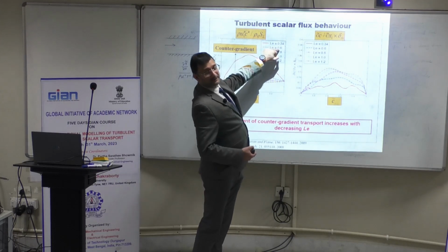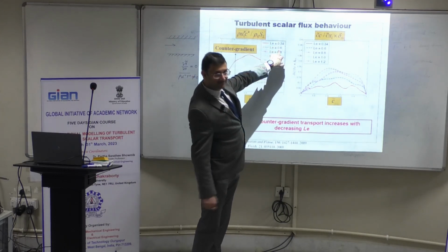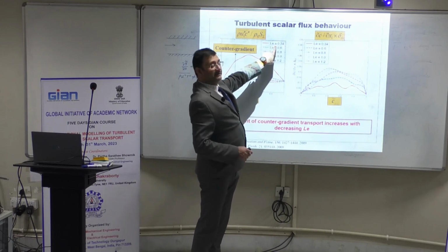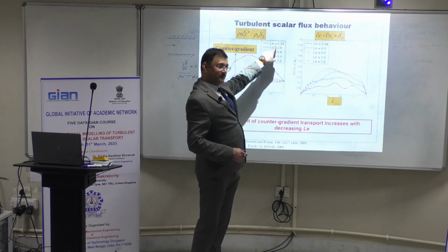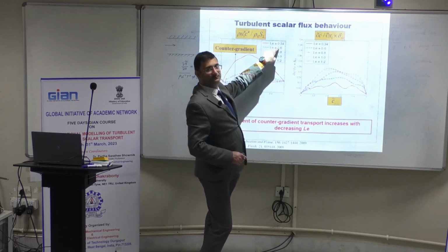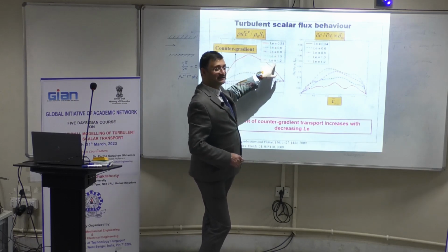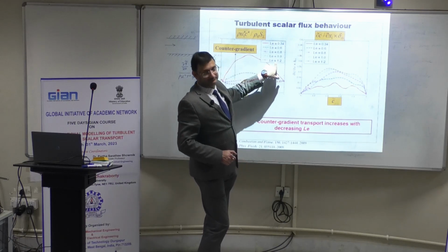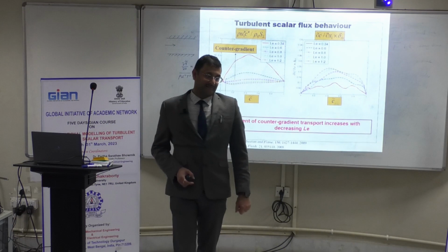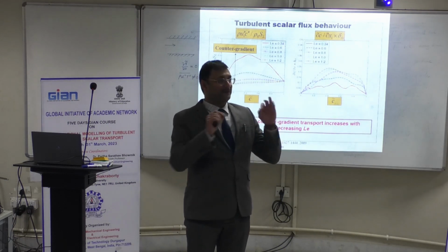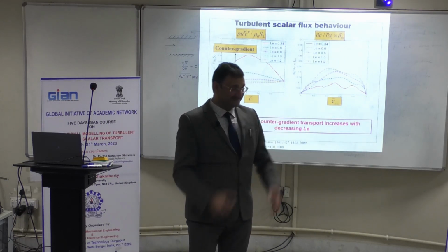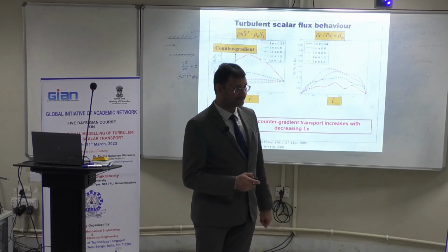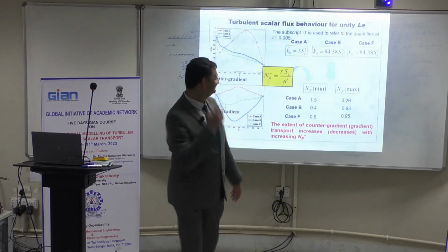Here you have about 40% hydrogen by volume mixed with methane. This is a hydrogen air flame for equivalence ratio 0.4, and this one an ethylene air flame for equivalence ratio 1.2. Turbulence is exactly the same. The fuel properties are different, in other words, material properties are different. Clear?